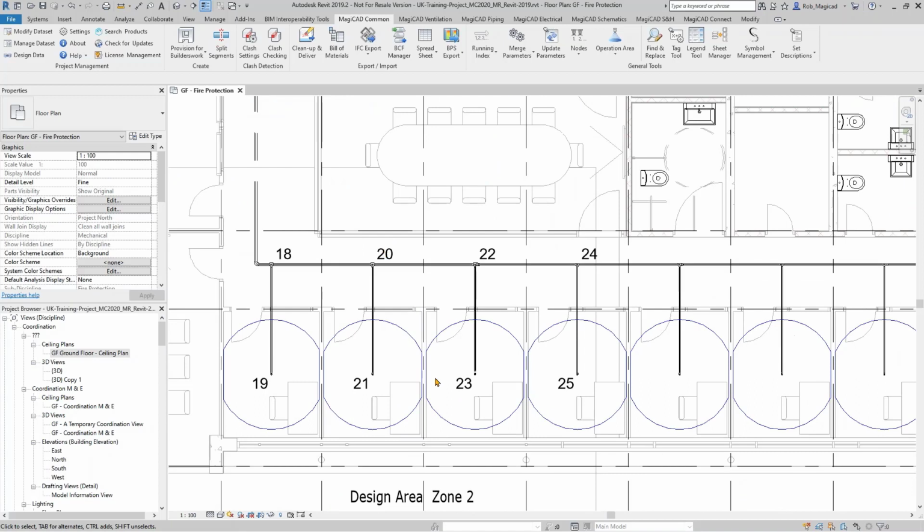So it makes you aware of the coverage of that sprinkler. That's obviously a function of a radius, which is a function of the area of coverage. If you're happy with that, fine, but it may be that you wanted this to extend out of the room, and actually that isn't going to be compliant. Then obviously you can change that to have an increased area of coverage, so that would be to the corners of that space.